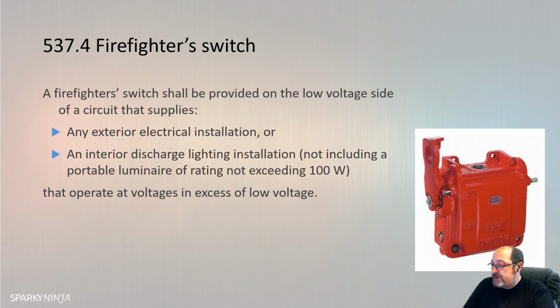The information shall be distinctly and durably marked on the firefighter's switch in a position where it can be clearly seen by a person standing on the ground at the intended site without opening the enclosure and when the switch is installed. On and off positions, the letters not less than 10 millimeters high, and letters reading firefighter switch or fire switch in letters not less than 10 millimeters high. Once installed, the handle off position will be up. So down is on, up is off.